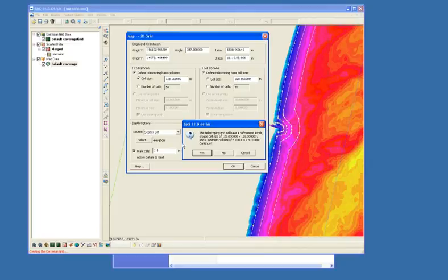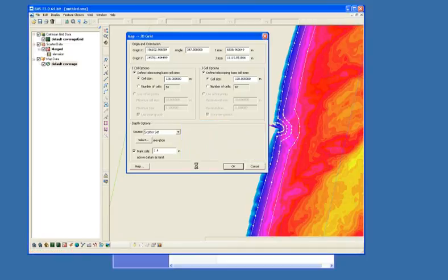So we've added this little double check just to make sure that you can stop it before it starts. If this number is really large, then you can say, no, I don't want to continue, and you go and find the ones that you have not set. But for right now, we have a minimum size of 8 meters up to 128 meters with 4 total refinement levels it figures out. And then you say, yes, I'm going to continue.